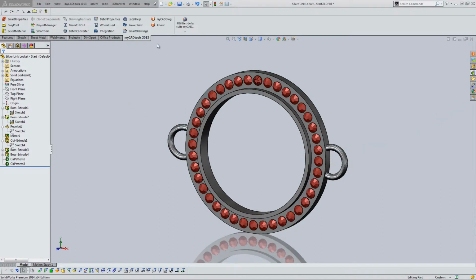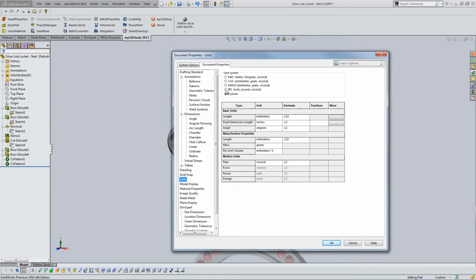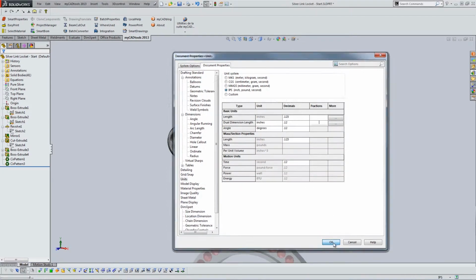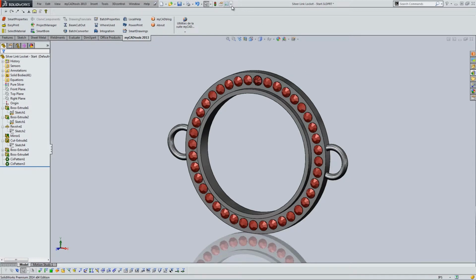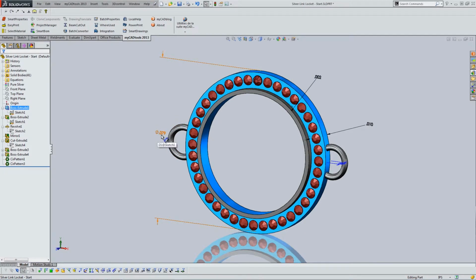All right, so let's follow my plan of attack like we used last time. We're going to change the units right away to the right unit type, and that will be inches. So I'll change that right here to IPS. Okay, that's the first step. Then I like to always take a look at the numbers here. For example, this is really 0.079 currently. It needs to be 2 inches. So we're going to convert from that to 2, right?